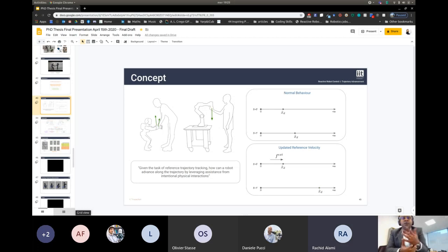You can design the controller to reduce certain joint torques. For example, in the stand-up task, you can use this interaction and ask the robot to apply less joint torque at the knees when the interaction is helpful. I would say that in this case, the robot will be more cautious somehow. It will save energy. It's more like a conservative approach.